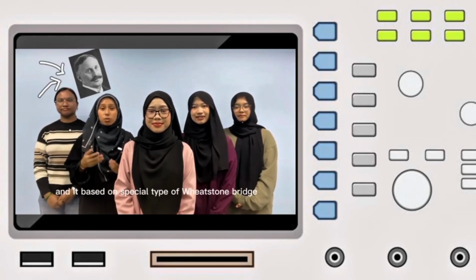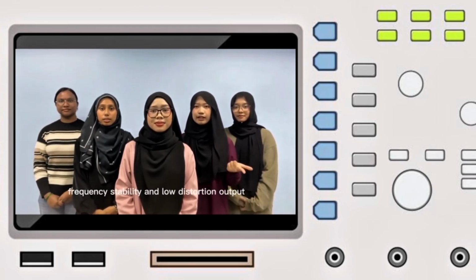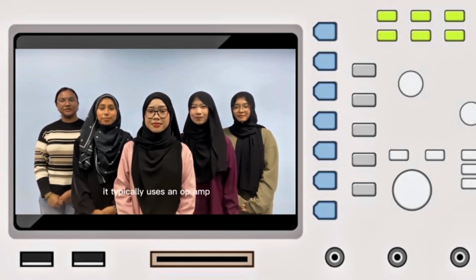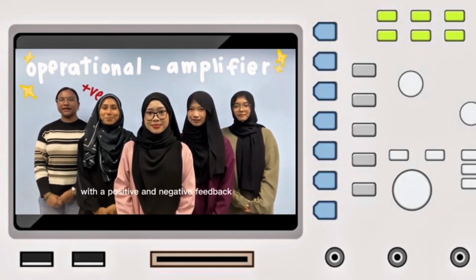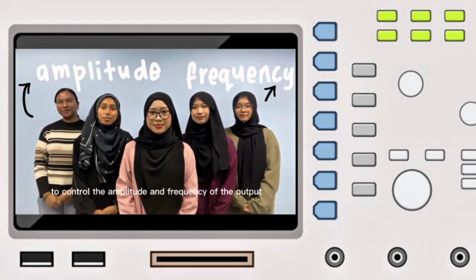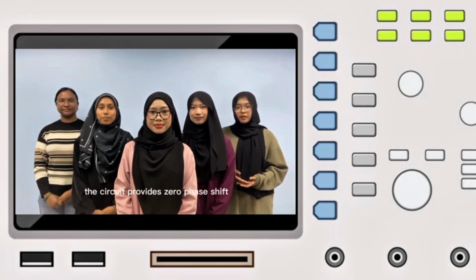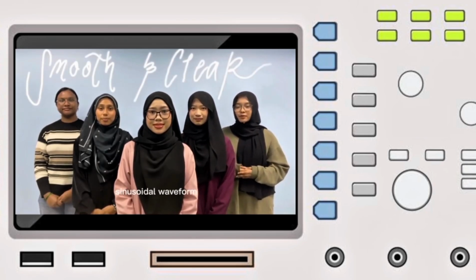Okay, today we'll be introducing the Wien bridge oscillator, a well-known circuit used to generate the pure sine wave. It was developed by Mr. Wien and is based on a special type of Wheatstone bridge called the Wien bridge network. This oscillator is widely used because of its simplicity, frequency stability, and low distortion output, especially for audio signals. It typically uses an op-amp with a positive and negative feedback to control the amplitude and frequency of the output. At its resonant frequency, the circuit provides zero phase shift, producing a smooth and clear sinusoidal waveform.